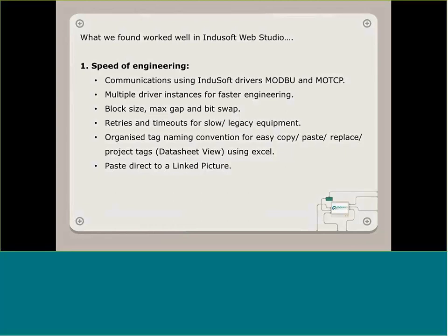We could also change the max gap size and do some bit swapping for a whole driver sheet without having to do individual ones. We also found that we could do retries and timeouts for slow or legacy equipment without having to tie down other parts of the system. So we could do that by setting up the same Modbus driver with two different settings.